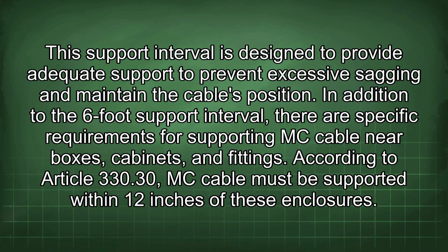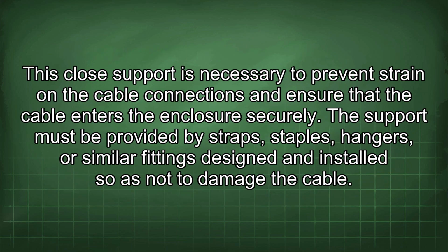In addition to the 6-foot support interval, there are specific requirements for supporting MC cable near boxes, cabinets, and fittings. According to Article 330.30, MC cable must be supported within 12 inches of these enclosures. This close support is necessary to prevent strain on the cable connections and ensure that the cable enters the enclosure securely. The support must be provided by straps, staples, hangers, or similar fittings designed and installed so as not to